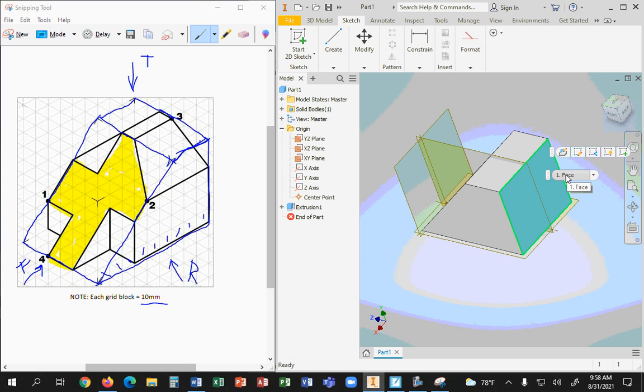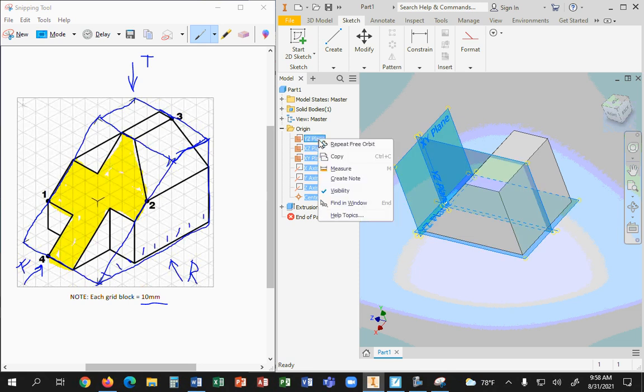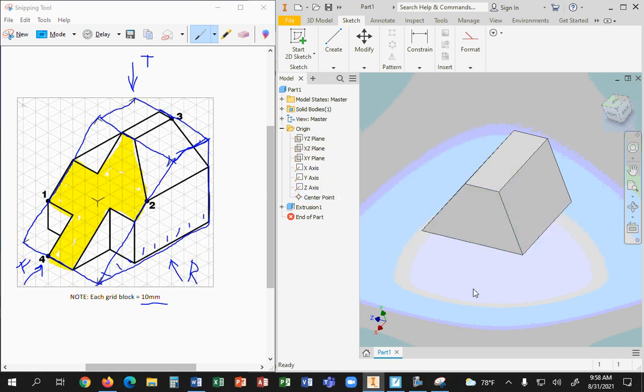If you have the other practice or the other habit, you're not going to like the way I'm going to say it, but I'm going to say it. It's your problem. Because it actually creates problems. So my word of advice, after you make your basic shape, everything else needs to be built or cut off of that shape. No longer do you use the planes. To make it very clear on that subject, I'm actually going to turn all my planes off. Every single one of them. So now you don't see them again. Cool? Ignore them. You want to use the model now.